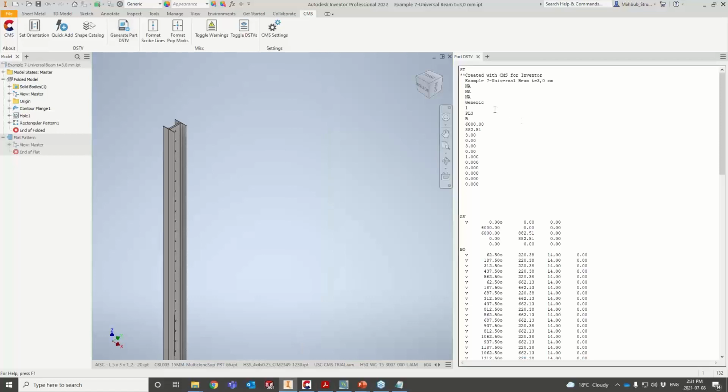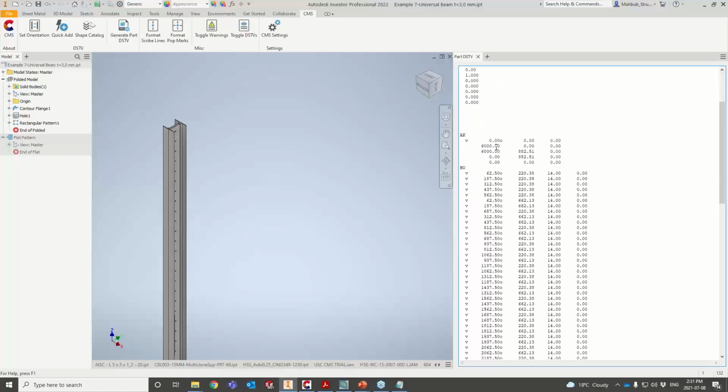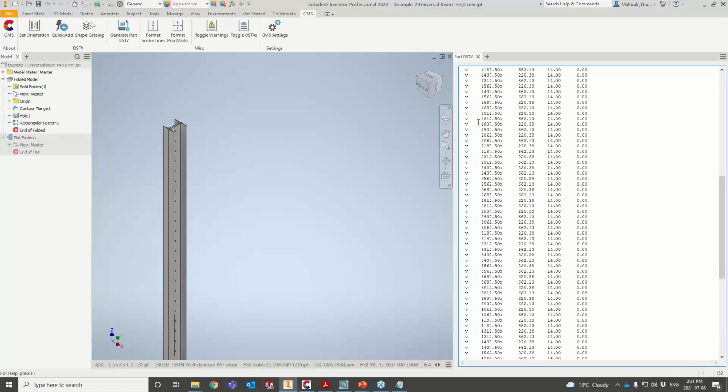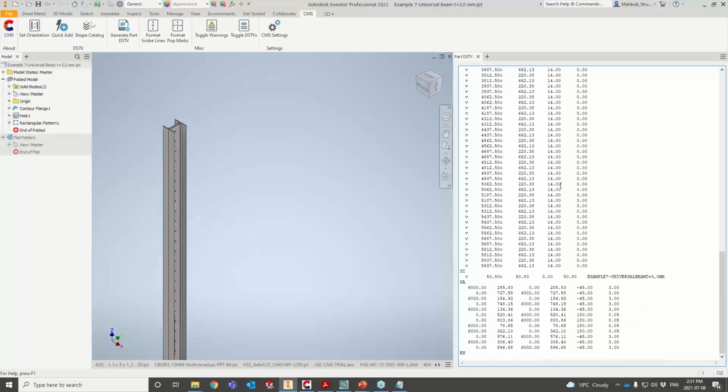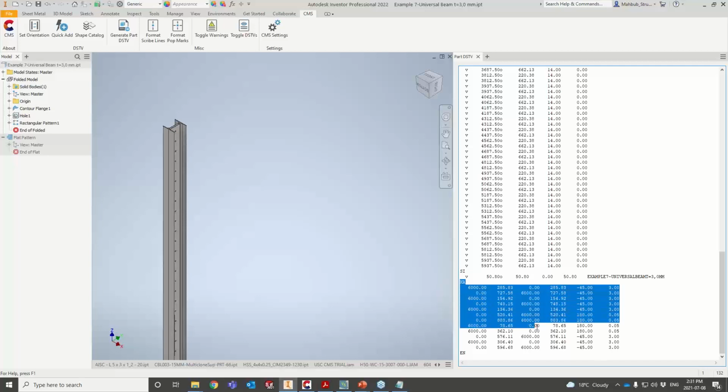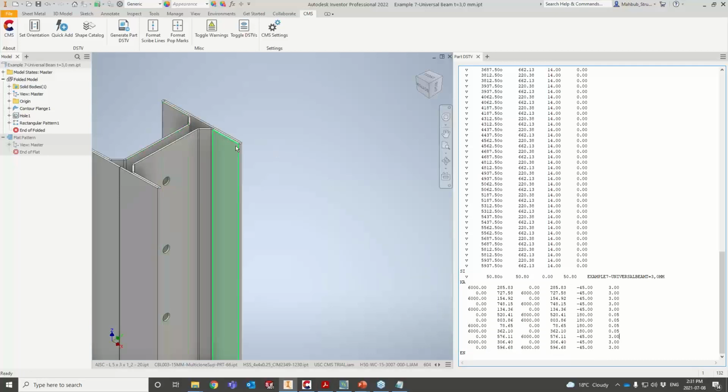As you see, I get a plate which is 3mm thickness, and I have all the drills listed here. I have a bunch of drills, and I stamp my part number on a default position. At the same time, there are the KA operations, which are the bending. So it gives you all the bending operations that have been done on the whole part. Okay, so it's super powerful, and this is really something that you can use to save a lot of your time.